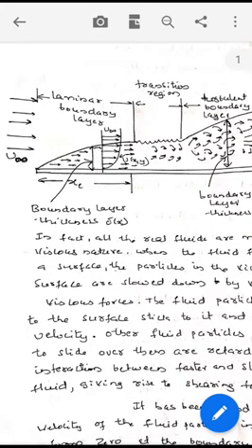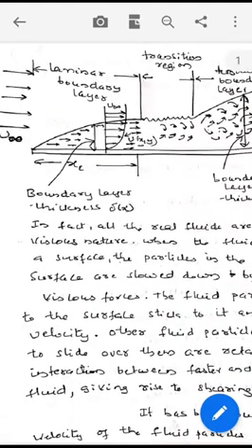the vicinity of the plate will be retarded due to skin friction between the plate and the fluid. The particles which make contact with the plate will stick to the plate and will have zero velocity.